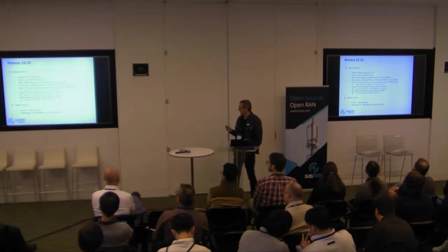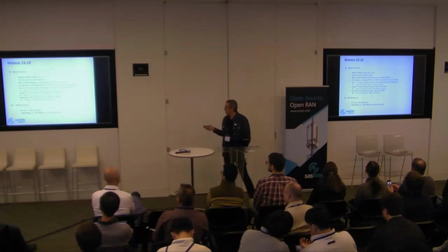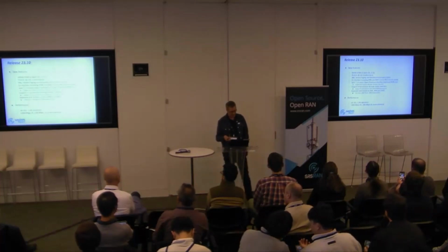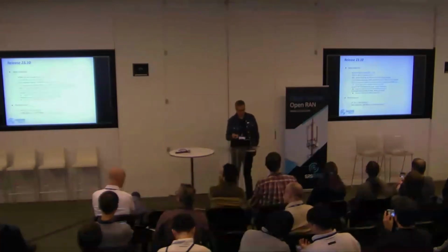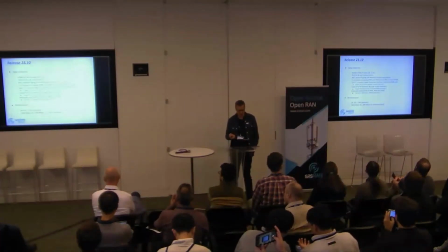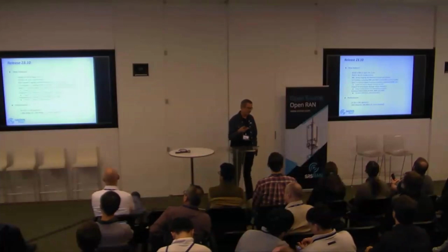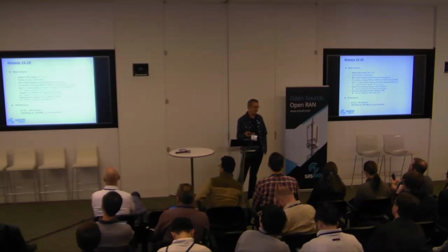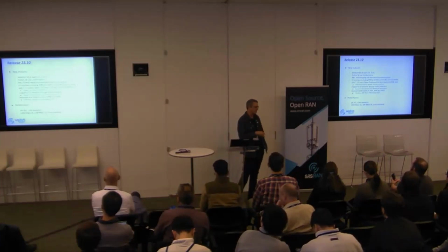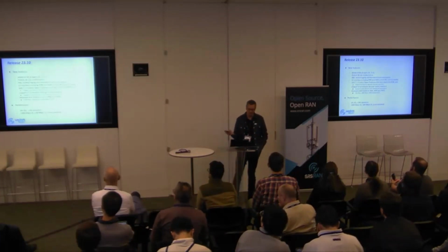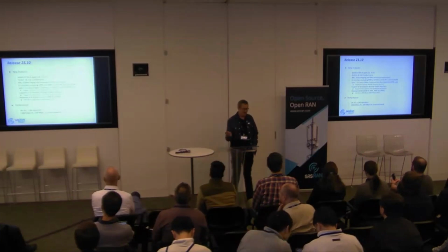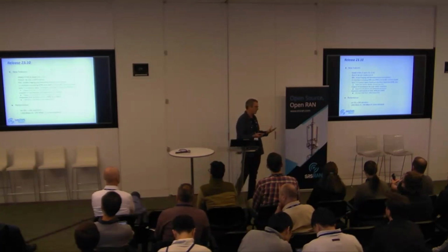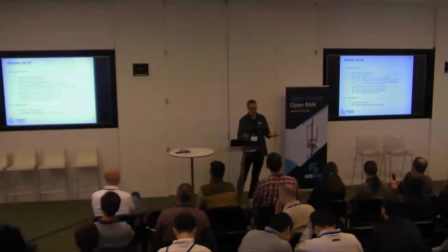From April to October, the most important one was the 4-layer downlink. Not only the MIMO capability, the most critical thing there is the performance. It doubles from 700 to 1.4 gig. And once your algorithms are already very efficient, you can only achieve that by parallelizing more, but parallelizing more always brings more complexity.